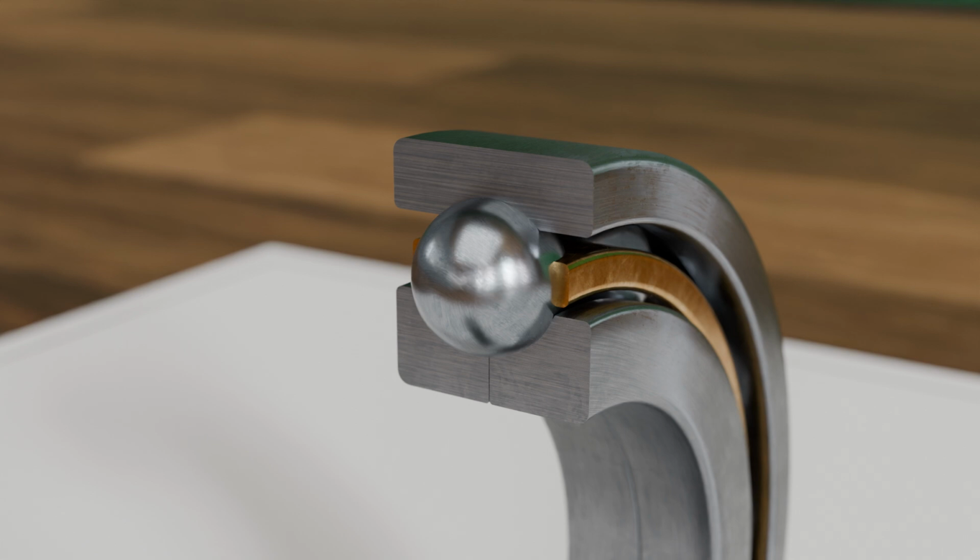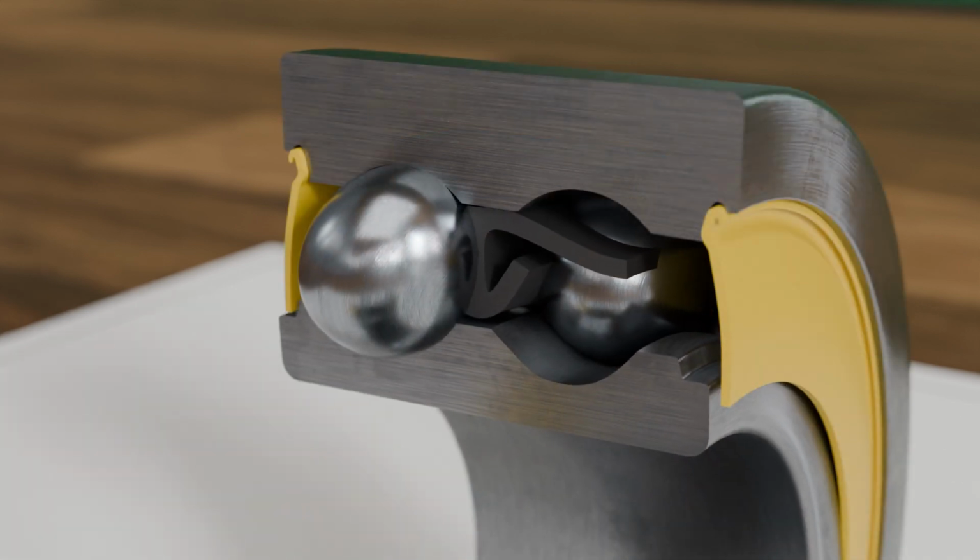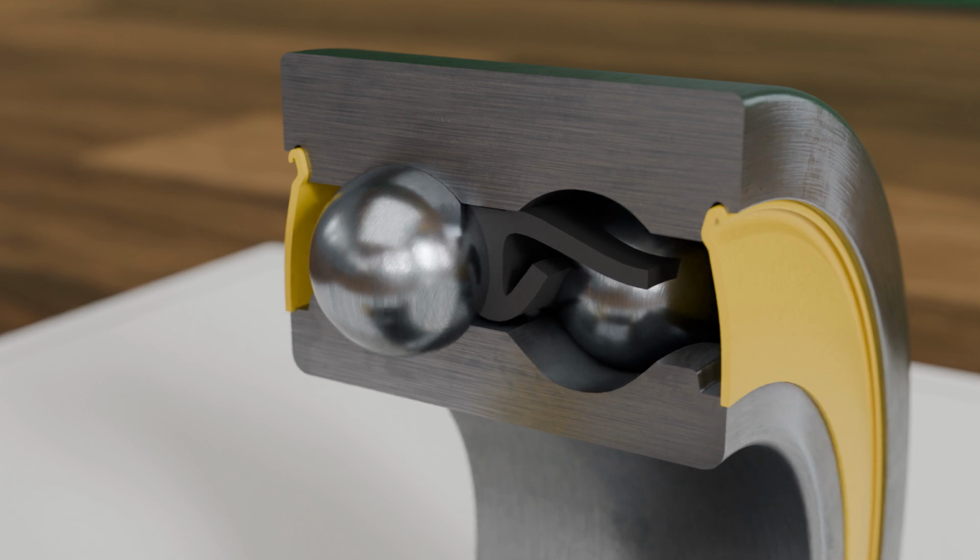Single-row ball bearings can compensate small misalignments of the shaft because they are less rigid. Double-row ball bearings cannot do this well because their rolling elements would be damaged. In certain applications, a deliberate shaft misalignment is required alongside high load capacity, or misalignments occur during operation due to thermal expansion, housing settling, or shaft bending. For such cases, so-called self-aligning ball bearings are suitable because they are designed to reliably compensate for misalignments.